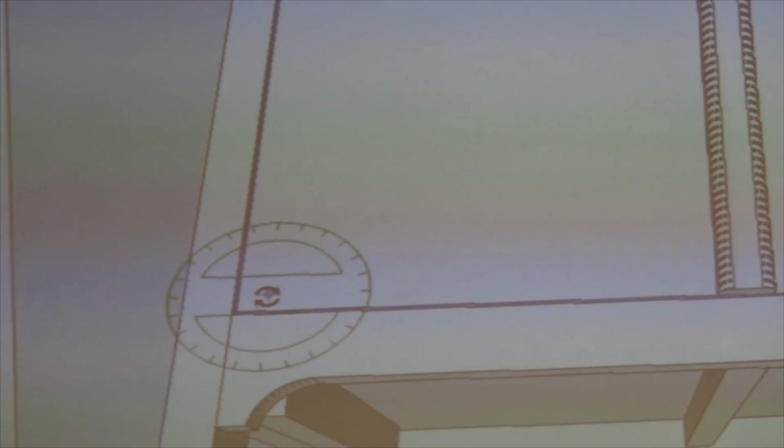See that? This is a little bit difficult because we want to make sure we get on the very bottom of this. We want the blue axis. I could have zoomed in just like I did there to be able to find the blue axis so I can make that rotation. But there's a quicker way to do it rather than zooming in like that. You can simply find any other surface that is in the plane that you want.